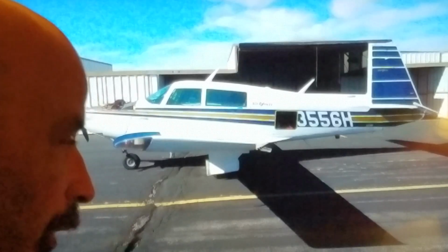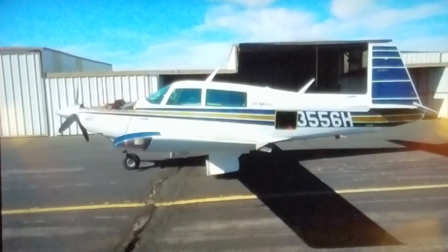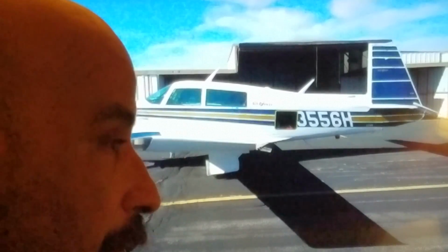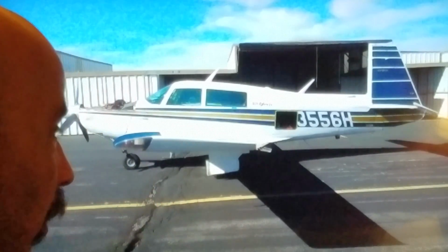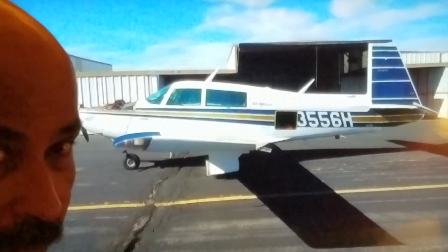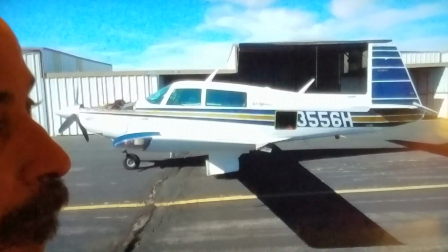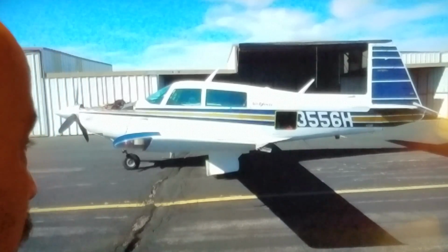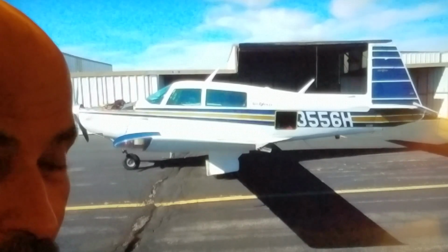I also have the top cowling removed here because when we go into the engine section, I want to show you the components of the engine. This aircraft, again, is a fixed wing, single engine aircraft with retractable landing gear and a constant speed propeller. This is called a complex aircraft rather than a fixed pitch propeller. The propeller on this aircraft has a variable pitch.